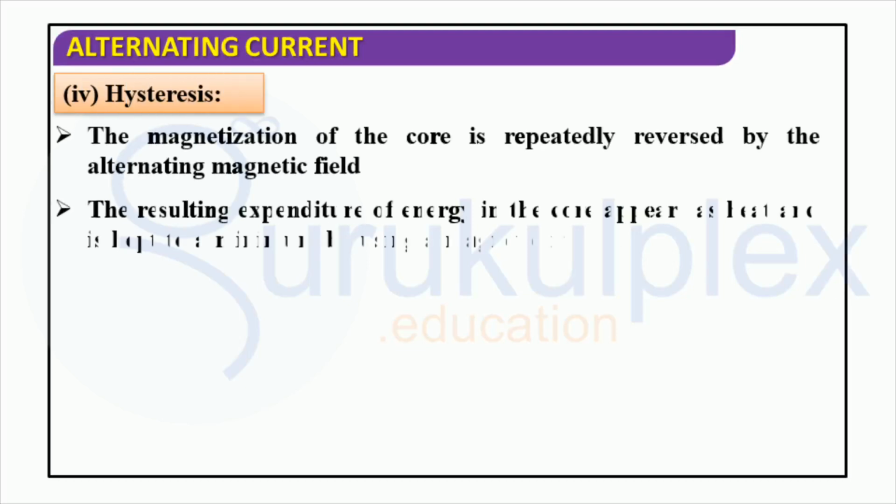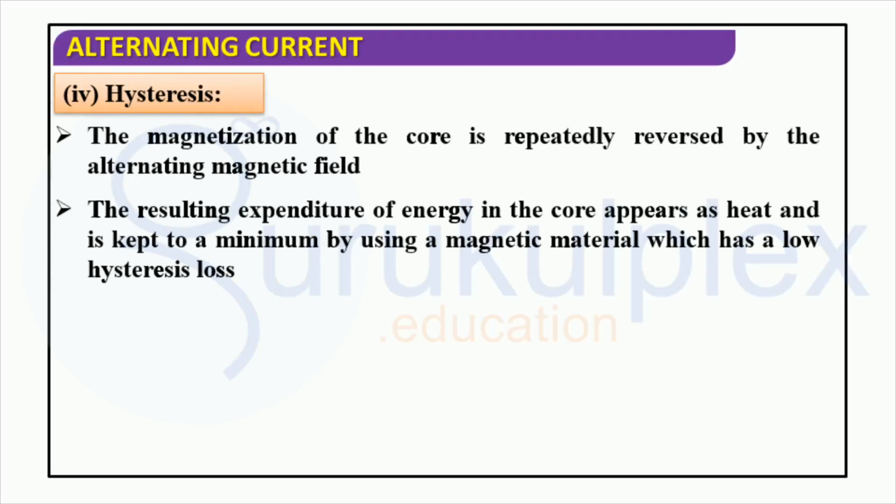Magnetic hysteresis is a significant consideration when dealing with alternating current. Optimal performance can be ensured by selecting materials with reduced hysteresis loss, thus lowering the amount of heat generated in the core. This in turn reduces energy expenditure and optimizes operation.